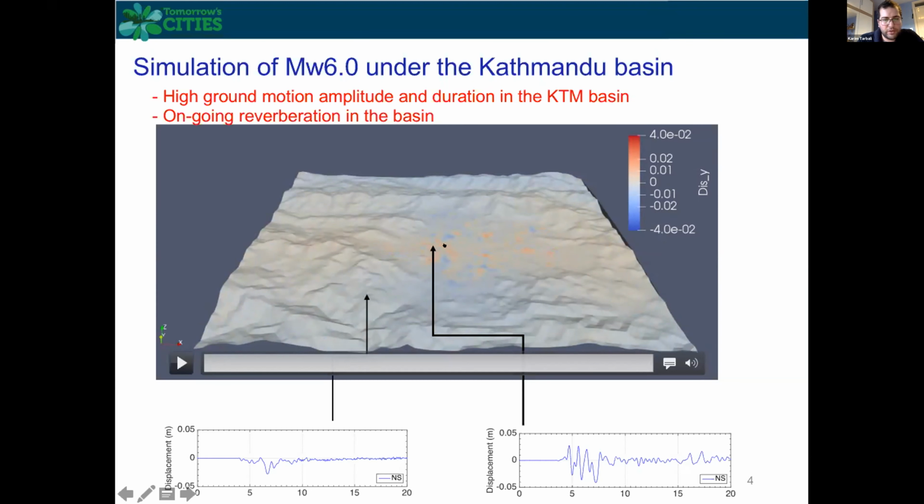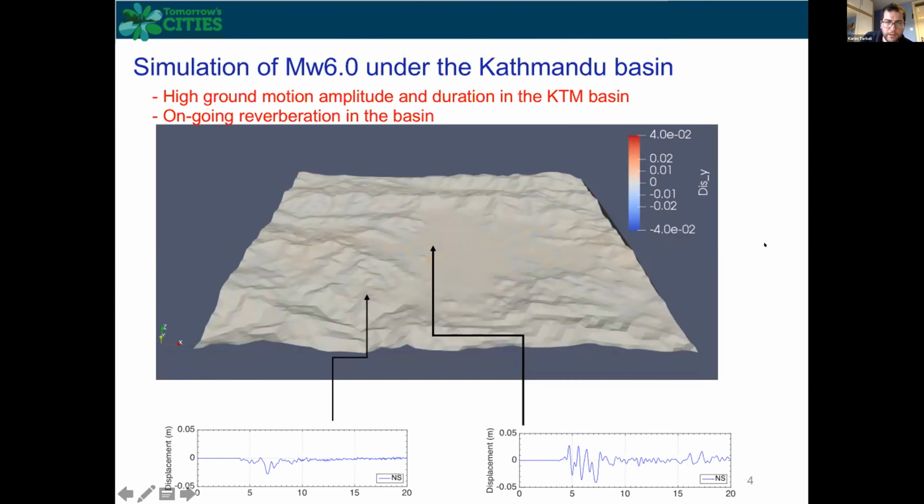And imagine if you have a structure here, there, you can assess the performance of and the damage to the structure using these ground motions, and obviously that ground motion that you will use for the structure here will be different. So this type of physics-based models are capable to incorporate the region and site-specific details of the seismic hazard.